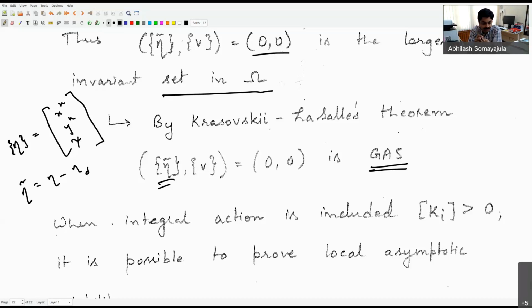Sir? Yes. What if it is between two such points, like two desired points? I'll only be specifying one desired point at a time, right? At a time, I'm tracking only one desired point. After I have reached that waypoint, I'll track the next one. But at a time, I'm only giving it one input. In fact, you will see that in our line of sight, we may not actually give the waypoint as the input. We may give some look ahead distance and some point on the path as the point which I want to track instantaneously. Doesn't matter.